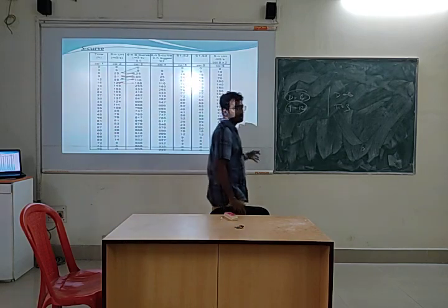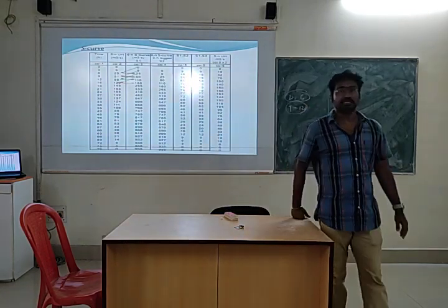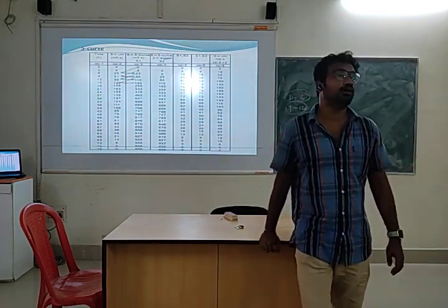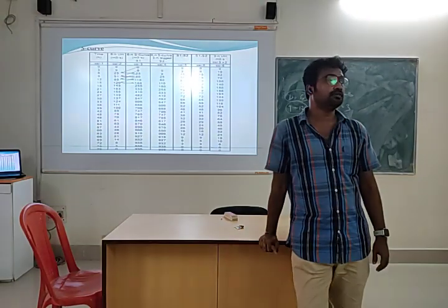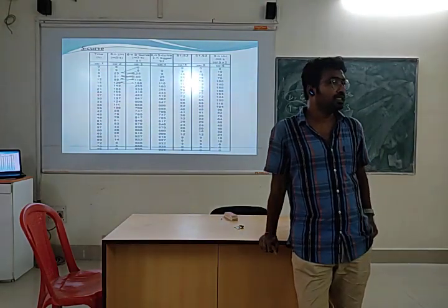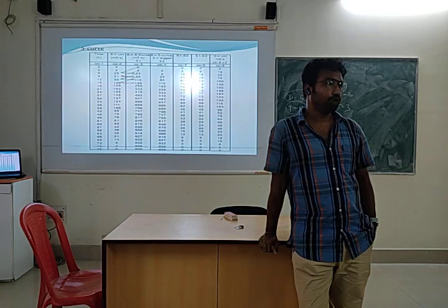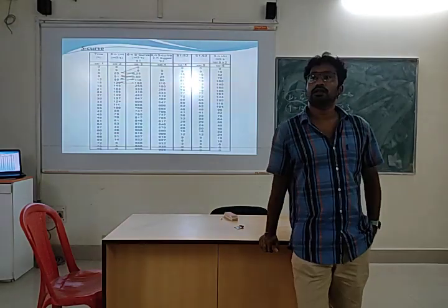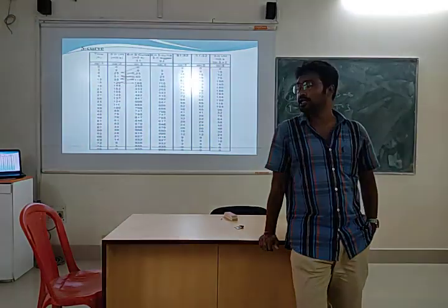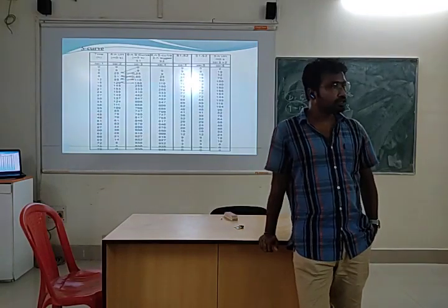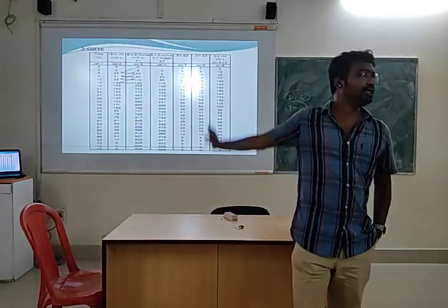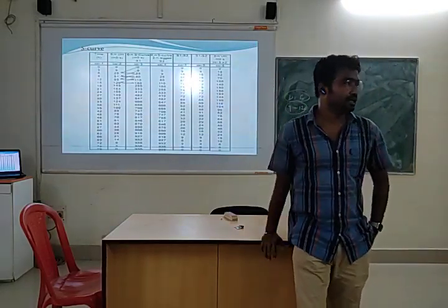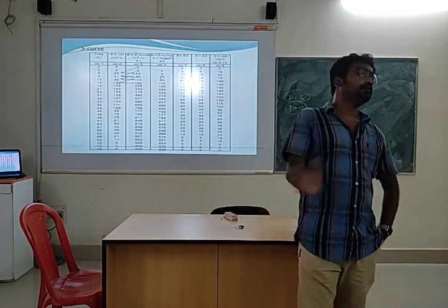So that was an example where the T was not an integer multiple of D. That was a fractional multiple of D, right? T was equal to 0.5 of D. So for those cases where fractional multipliers are there, what can we do? The procedure will be the same, right? We can follow the same procedure, finding the S curve, S1 and S2, then we can easily find out what will be the unit hydrograph for the different duration.